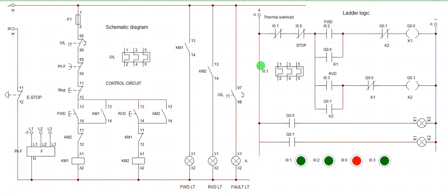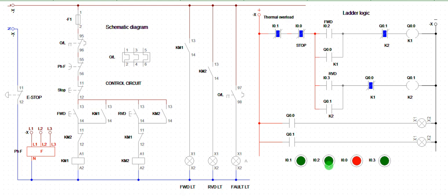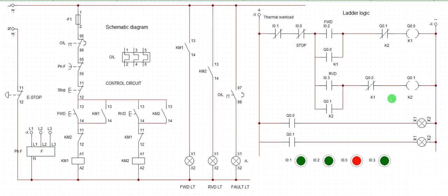So in that case, I don't need this block. I don't need that block. So put on the system. I can create the fault from here. Once I create it here, then this one will shut down. But that fault is actually coming from the overload block. All right. Okay. So that is how this logic functions. This one is for overload to cut off during friction or a resistance from a mechanical mechanism.